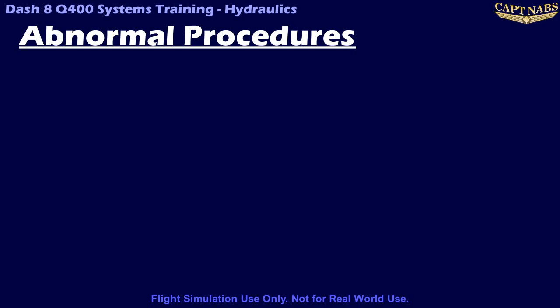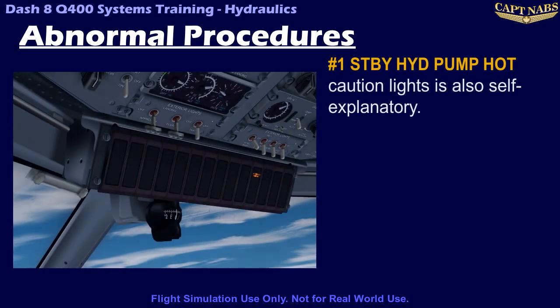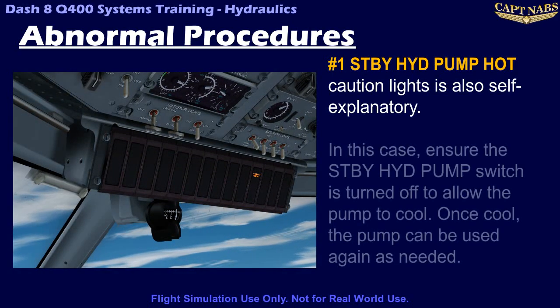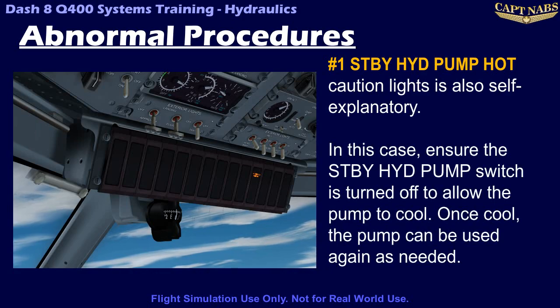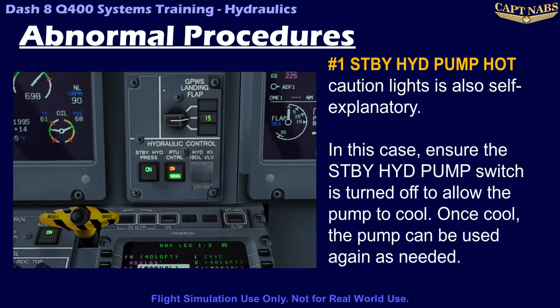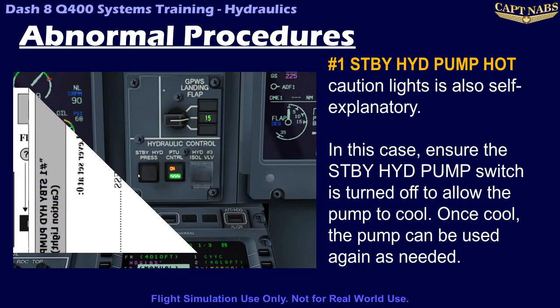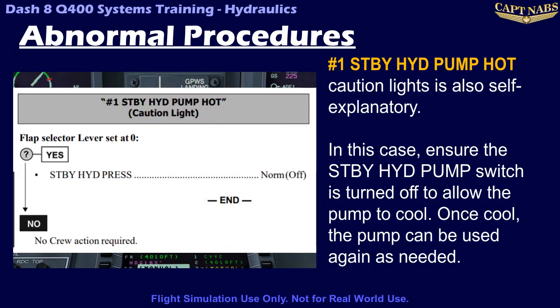If the number 1 standby Hyd Pump hot caution light illuminates, the checklist is again quite simple. If the flaps are already up, turn off the pump and continue on. Hopefully the pump will cool itself once it is deactivated. If the pump does cool and the light goes off, it can be used again.